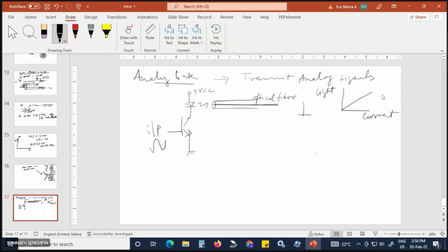And here one photodetector will be used. Photodetector is reverse biased. Here one minus some voltage, say minus V is applied, and across some resistance or load circuit, output, say it is resistance R. So this is the light, then in front of the optical fiber, you just connect the photodetector, which is reverse biased.